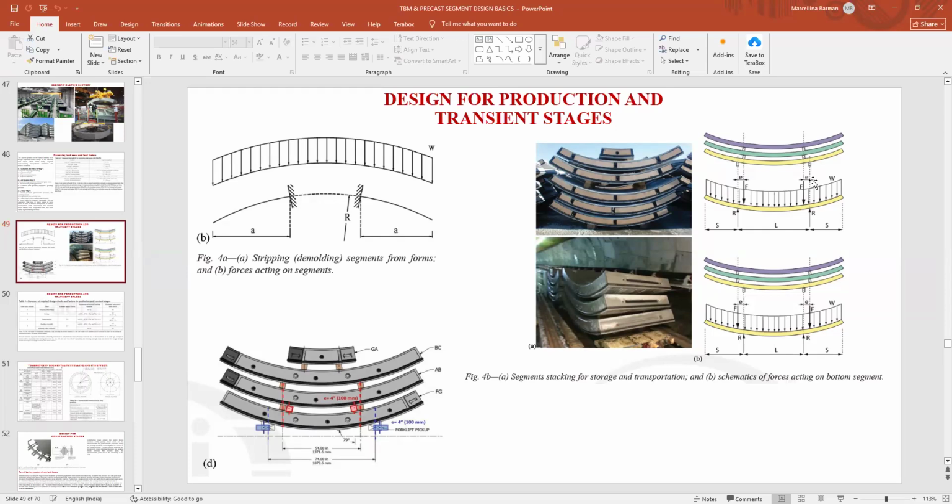So that is why, if it is a G plus 1 story building and if it is a G plus 5 story building, the G plus 1 story building is not vulnerable to the TBM movement. Because whenever we are checking the building health, we check in terms of the tensile cracks developed in the building. That is the building damage assessment. In the Burland criteria, we are checking the thickness of the crack or what category it is coming under.